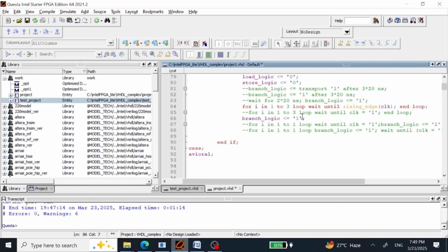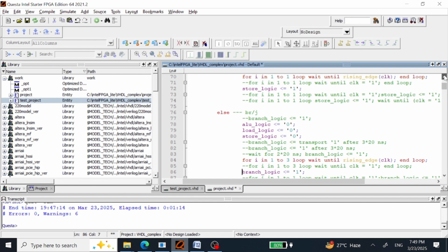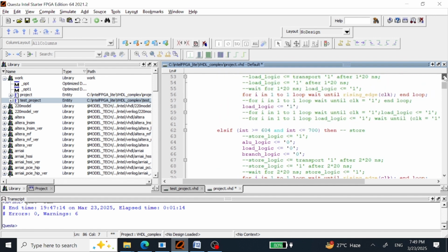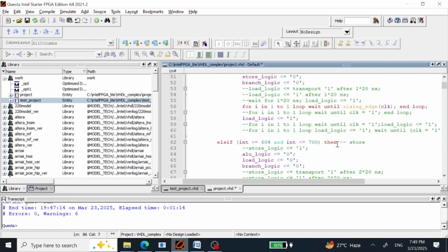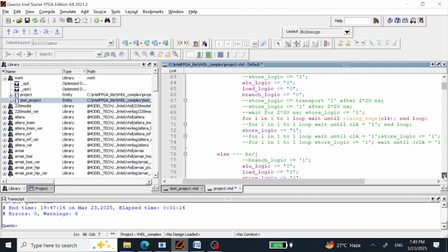So here you guys are also going to see that, I mean, even in these loops they are not running parallel. So I mean they are going to be in the series, so some cycles delay we are going to already get. That's why I am saying here from 1 to 1 clock cycle, and then I am saying from 1 to 1 for 1 clock cycle, but it is going to get 2 cycles delay.